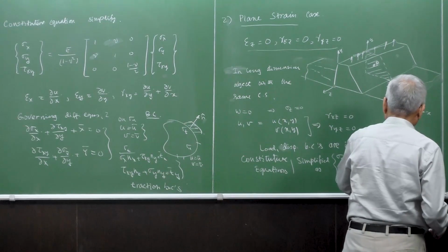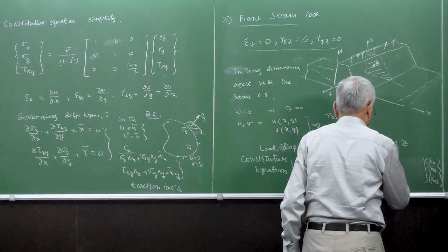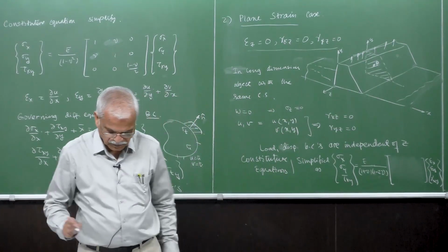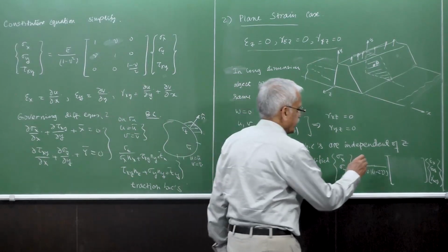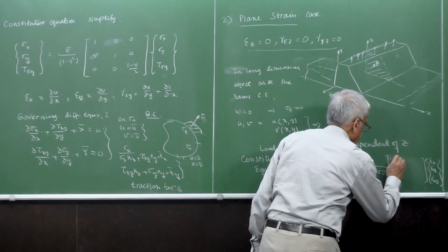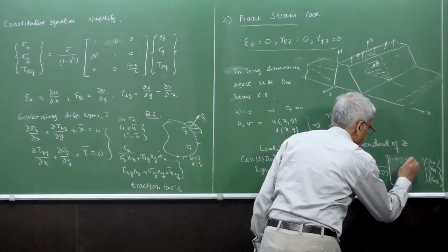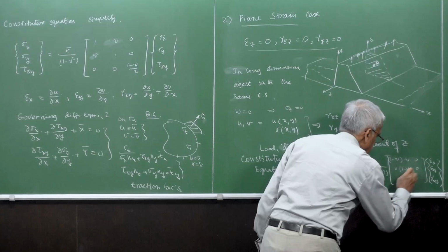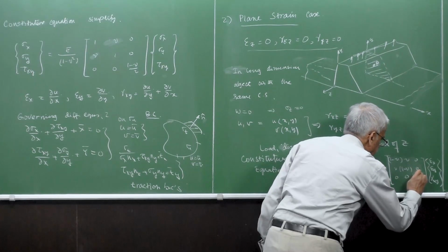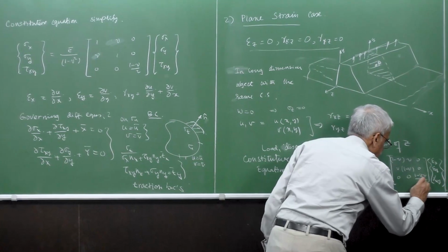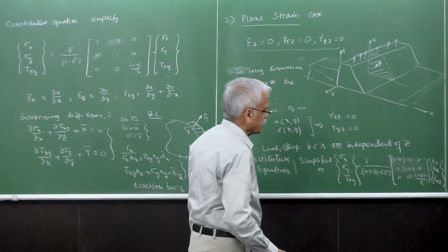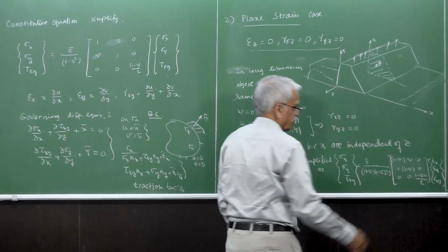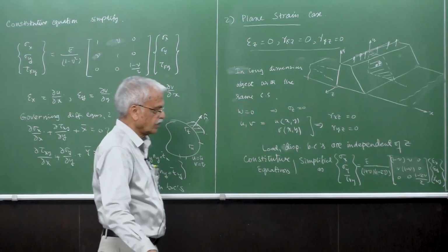Please make this change in the relationship here: 1 minus nu, nu, 0; nu, 1 minus nu, 0. Please make this small change. So the solution of the stress strain will look like this.